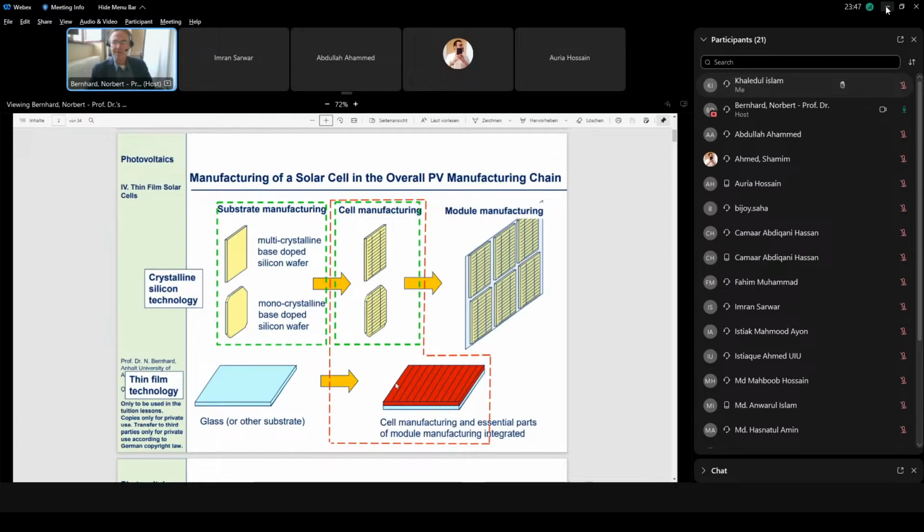Okay, here's a band diagram of the CIGS solar cell. It's quite similar. The only difference is that here the copper indium gallium diselenide has a lower band gap. Here again we have the cadmium sulfide, and therefore in this material system we have a step. But this step is also less than 0.1 electron volt, and of course there's also a certain uncertainty because it's not so easy to measure this step.